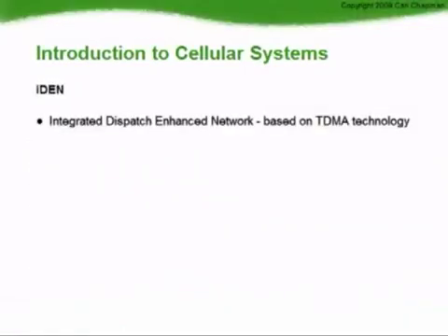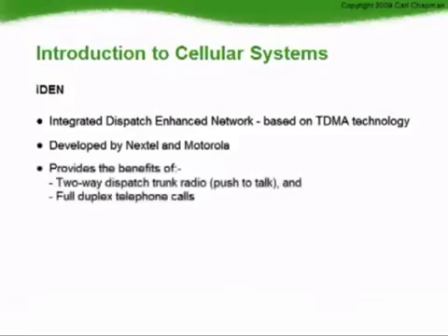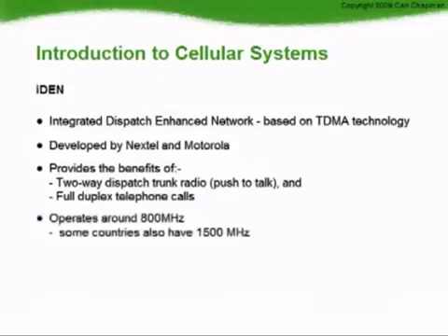iDEN, or Integrated Dispatch Enhanced Networks, are based on TDMA technology. The proprietary iDEN system was developed by Nextel and Motorola. It enables users to take full advantage of the capabilities of two-way dispatch trunk radio, commonly called push-to-talk, and full duplex telephone calls in one phone. This has been very popular with subscribers, as they can use the dispatch radio function to provide free phone-to-phone service.